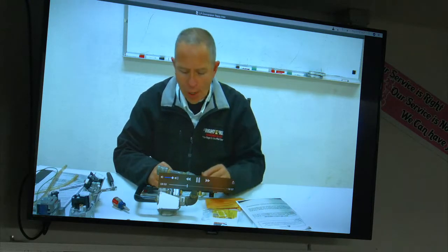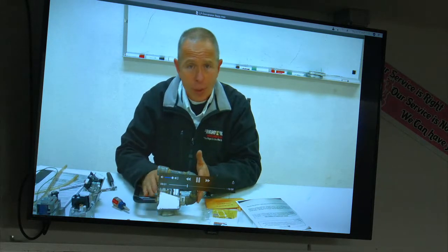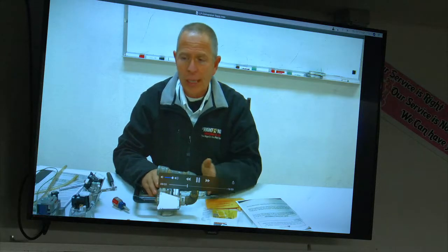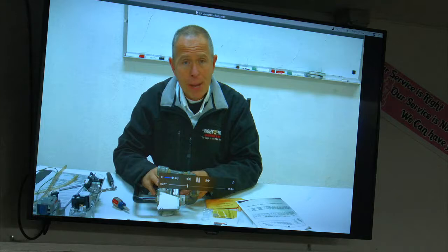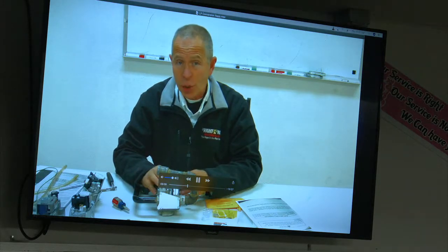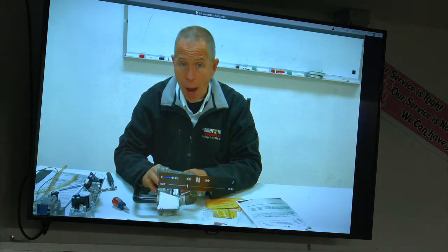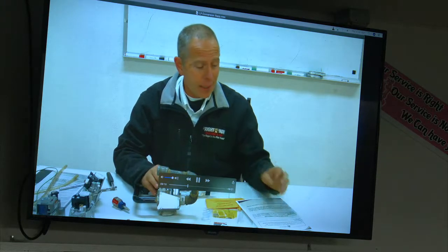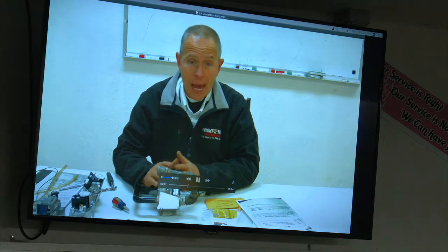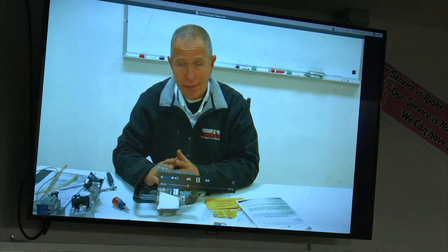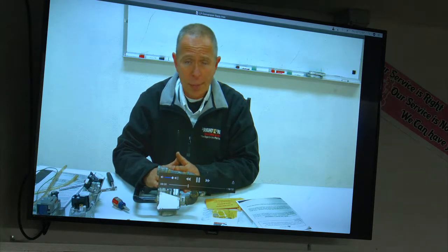Here's the key point. When we tie into this and put our meter on, we want to do the line side first, fire the furnace off, and make sure we don't have more than a 2-inch of water column drop from the incoming. If it becomes down to the minimum amount at the time of fire off, it may not have enough gas supply to run the appliance properly and will cycle and shut off.